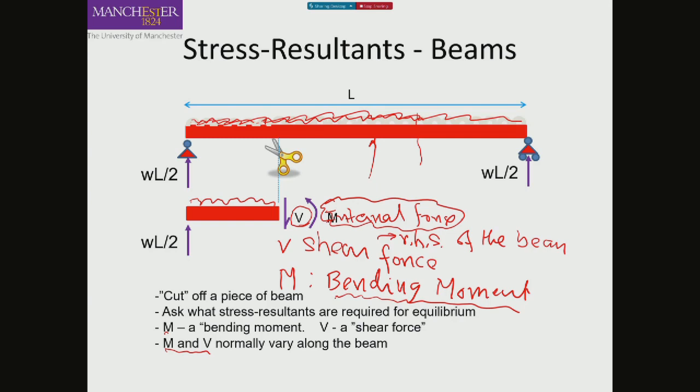If the stress due to bending and shear is less than the material strength, then the beam is fine. Beam can survive that load. If we find it is equal, then of course this is at a balanced position. And if the stress due to bending moment and shear force is higher than the material strength, that means the beam has failed. It cannot carry that much load.